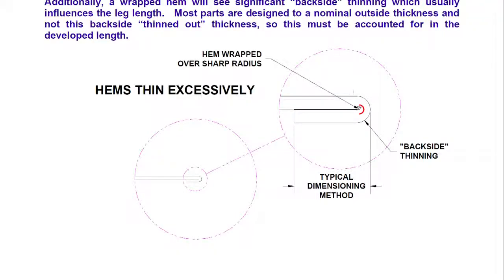If we have two closures like this, in between, you have a little offset here. And then in this portion you probably need a cut here and one more cut here to make sure that a grommet can be inserted here. In the power supply which I showed you the first time, it was there. So, materials are often tried and specified also, saying can you make a 180-degree bend.